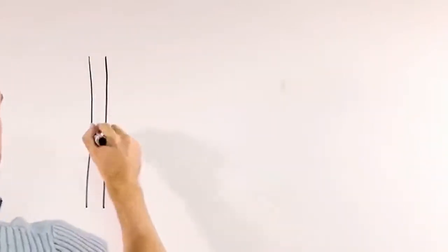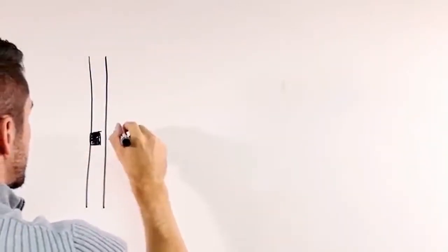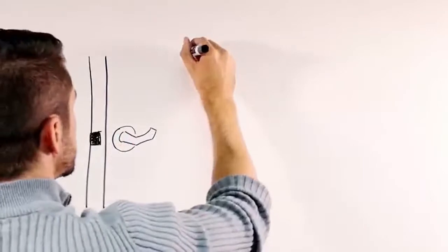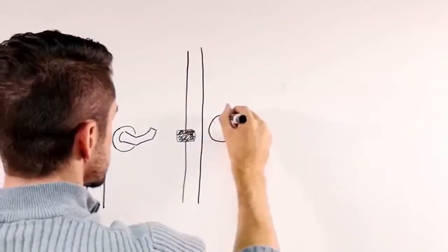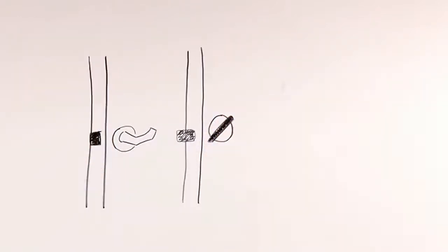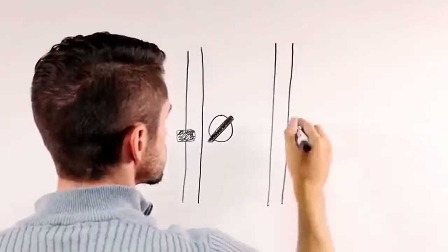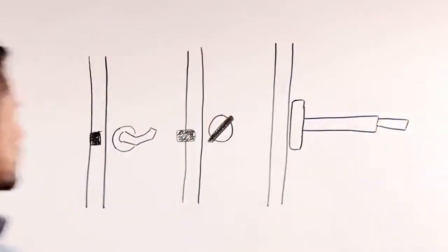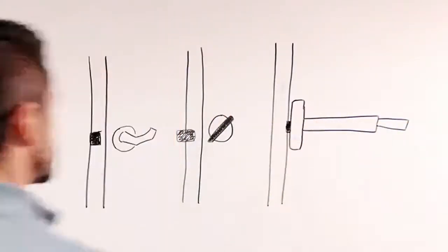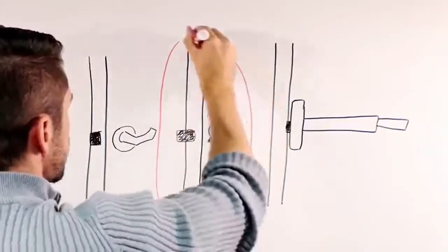The active latch bolt required for fire doors keeps the door closed against the pressure from a fire and the force of water from fire hoses. Door manufacturers require a minimum latch throw for lock sets and latch sets used on fire doors. Unless it is part of a lock set, a deadbolt, which can be held in the retracted position, would not provide a positive latch and therefore cannot be used on a fire door.